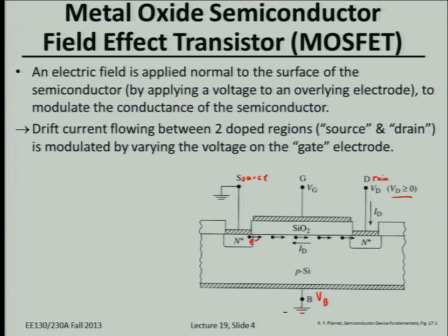Well, you have PN junctions between the source, drain, and the body. Exactly, reverse bias. That's right. So naturally you have these PN junctions here, and you really don't want to ever have current flowing between the body and the drain to cause the drain to start to conduct current. Okay, so to ensure that this body-to-drain PN junction diode never turns on, assume